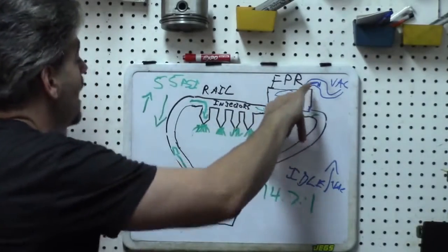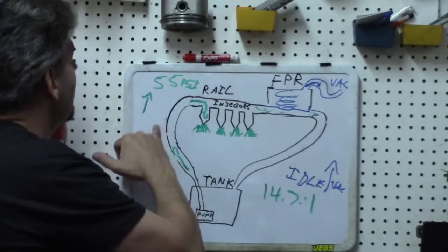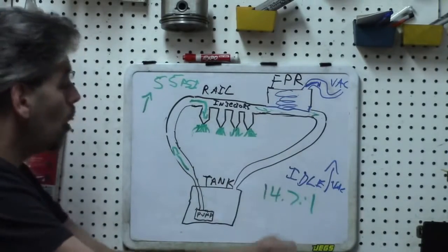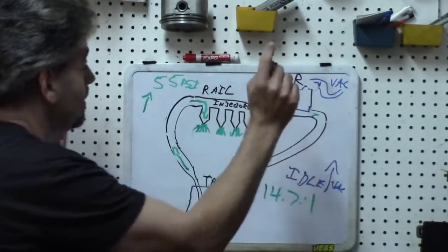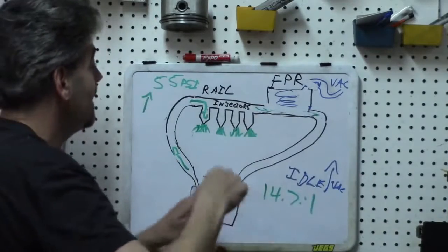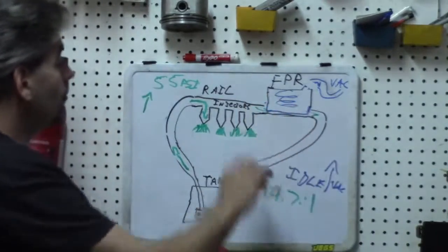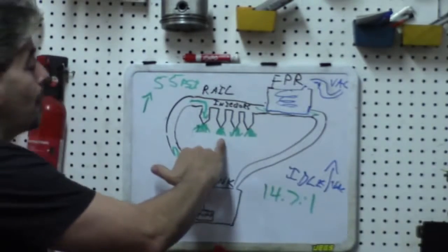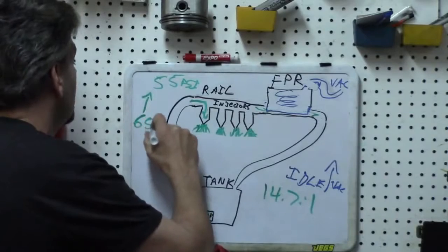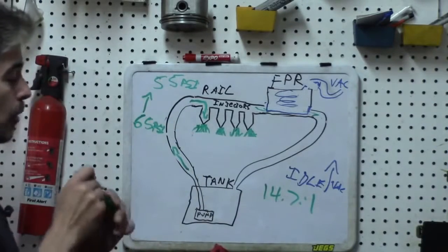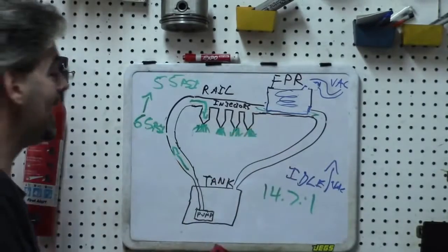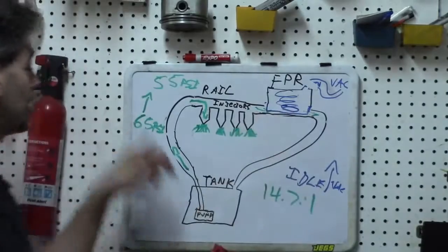If we were to remove the vacuum line and this engine is at idle, and we are seeing 55 psi at idle, and we remove that vacuum line, what would the effect be? Hopefully you can see that if we remove this vacuum line, the spring is going to push this diaphragm down, restricting that flow, but because the pulse length of the injectors has not changed, this is going to have a fairly significant effect on our rail pressure. So if the spring is working and the diaphragm is intact, if we pull the vacuum hose, you can see how mechanically we would increase the pressure at idle.